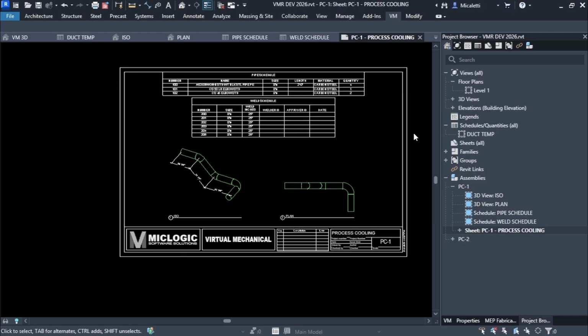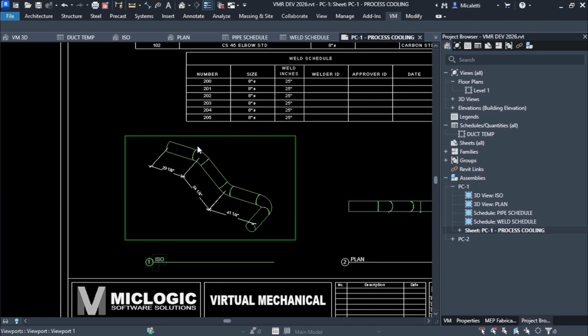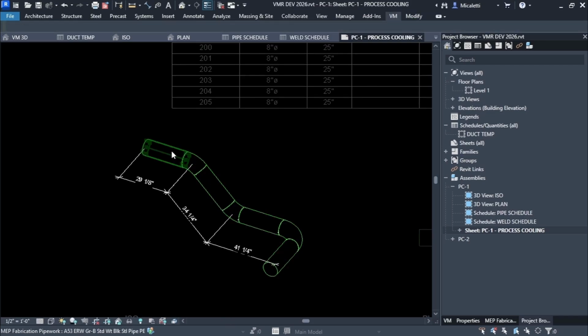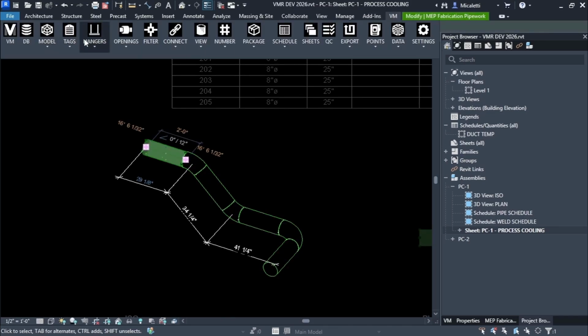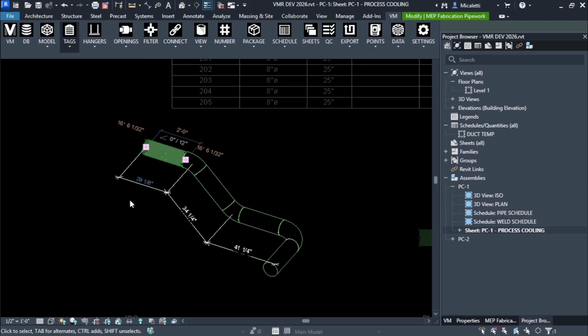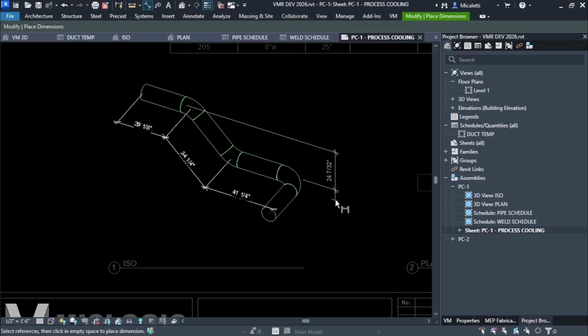If you wanted to get the height of the top and bottom piece, can you do that too? Because I see that you did the diagonal one. Yes, you can. So that's just a plane, right? So I'm going to go ahead and select, go in here, select this. But this time I'm going to go Dimension MEP, but I want my dimensions to stretch this way, right? And now I can go from here to here, right?